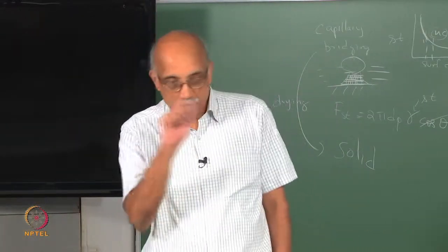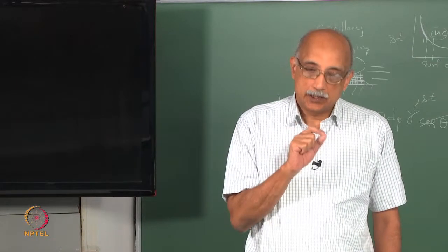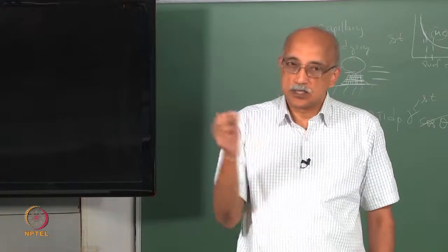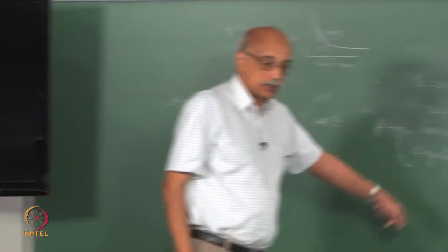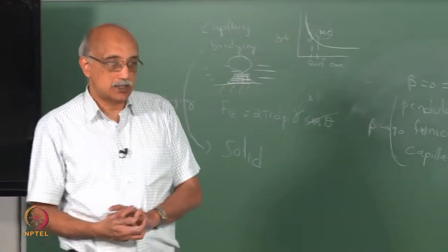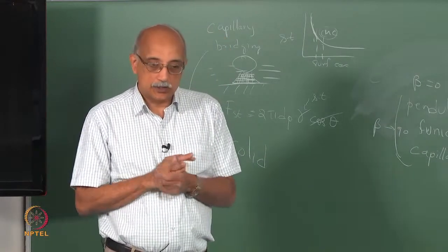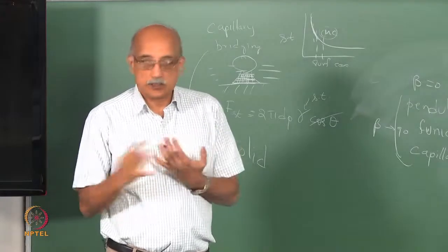However, as the particles start attaching themselves to each other, they can become like a second continuous phase, because they are not discrete particles anymore. So as the level of cohesion increases, the flow behavior itself can turn from a discrete or dispersed phase flow to a continuous phase flow.